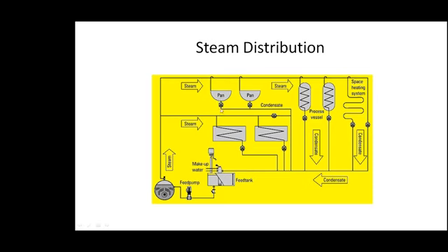But when you draw out this condensate, steam also will come. Like you have a coil in which steam is coming, steam condenses, condensate comes out, but steam also can come out. But we don't want the steam to come out. We want only the condensate to come out. So we need a special kind of valve which will allow only the liquid, that is the condensate, but not steam. That special kind of valve is called the steam trap.